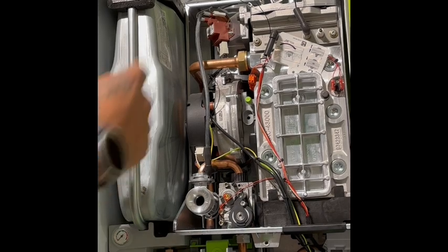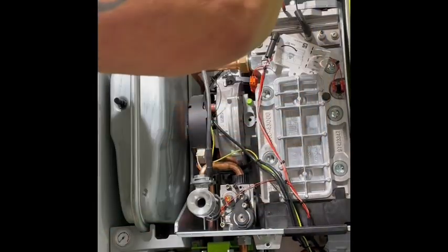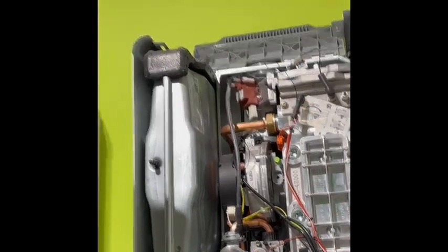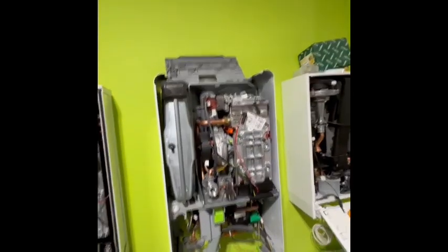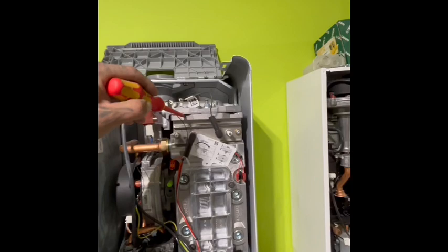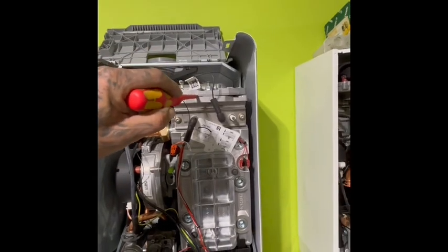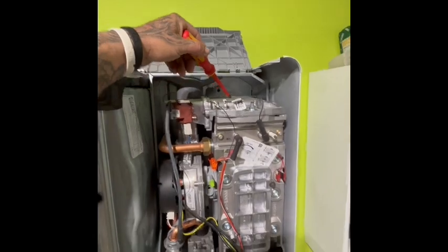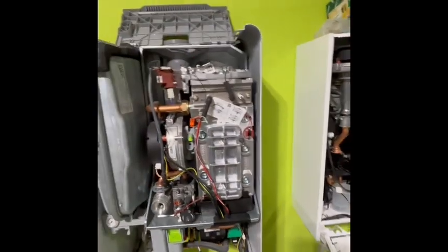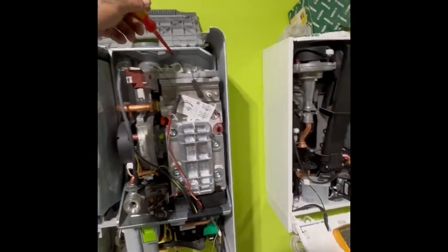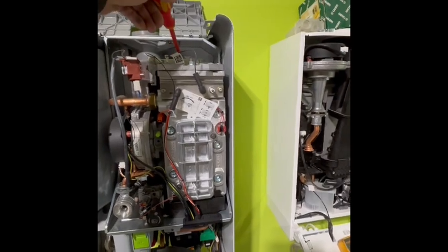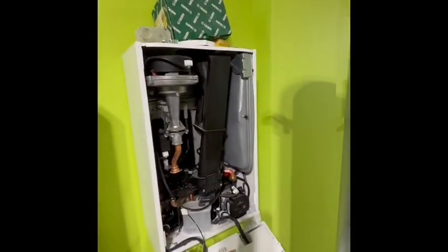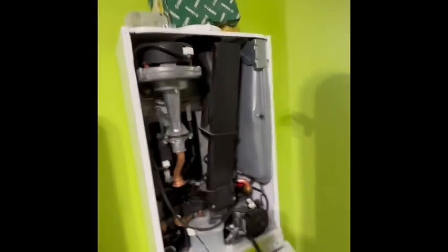So we're going to look at the burner for damage. Again, on this boiler, you've got to remember that seal's got to be replaced. A lot of the boilers on the market. So with this boiler, remember there's a burner seal on the top there that's got to be replaced. If you're going to check that, you want to be looking for damage. These are a fabric burner, if I remember rightly, downward facing. Check for damage. If I'm honest with you, I don't think I've ever had a fabric burner damaged on a Worcester Bosch. Burners on Ideals, what do?